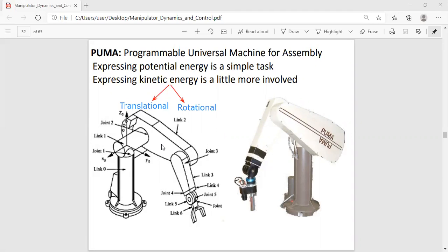So it's easy. What is actually complicated here, maybe you can guess it, is the rotational kinetic energy, which for 1 degree of freedom is 1/2 I omega squared. You only have rotational energy if your rigid body actually has some dimensions. For a point mass, for example, I is equal to mr squared. If r is 0, then your moment of inertia is 0, then your rotational kinetic energy is 0. So we're going to try to find how we can find the rotational energy, for example, of link 3. How can I find this rotational kinetic energy?